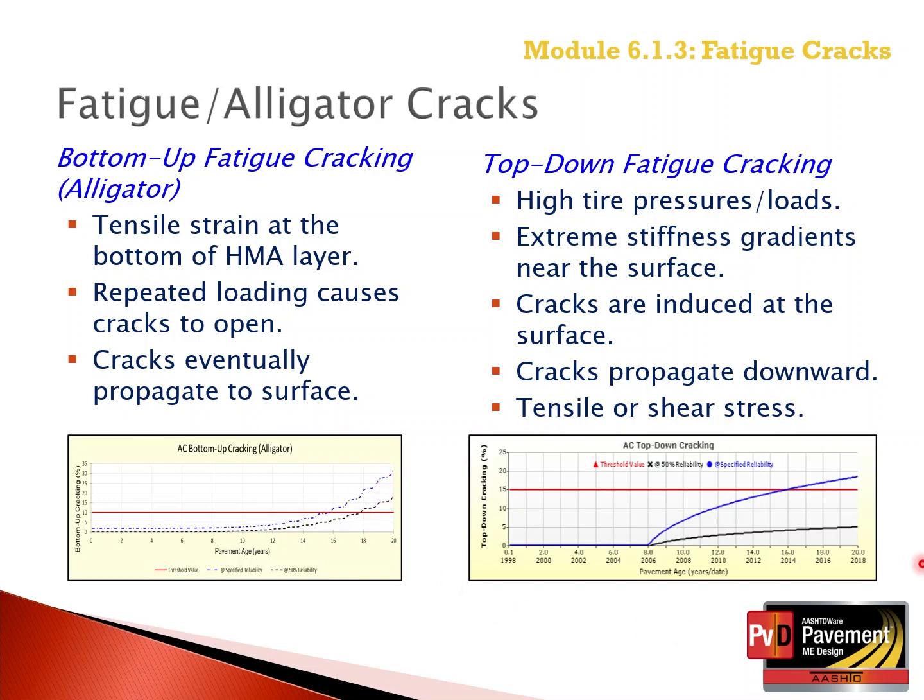So top-down cracks are dependent upon changes in the asphalt wearing surface, especially at the surface, for crack initiation, on the number of months it takes to initiate a crack at the surface, whereas that is not done at the bottom of the asphalt layer for bottom-up fatigue cracks. Both are caused by and determined by wheel load, so they are both wheel load related cracks.